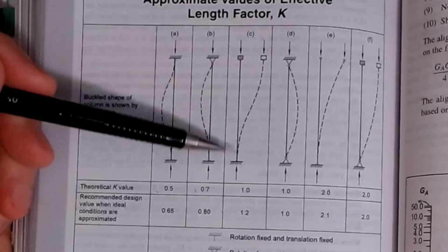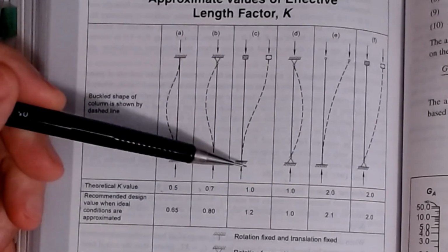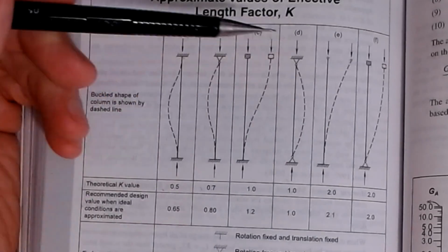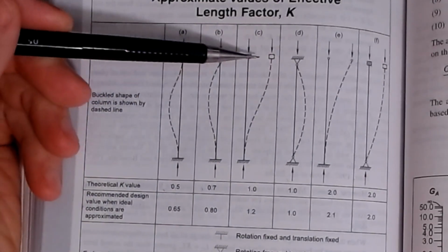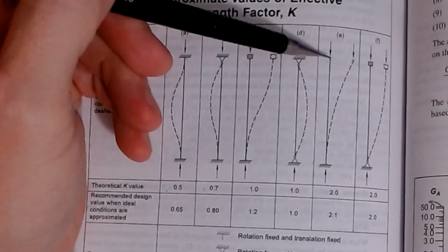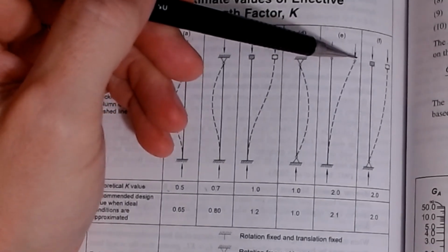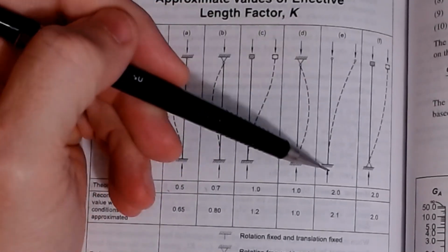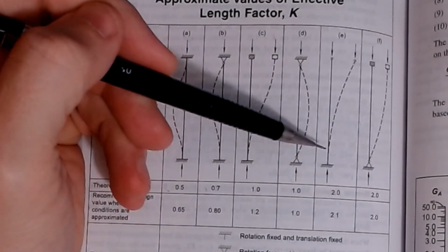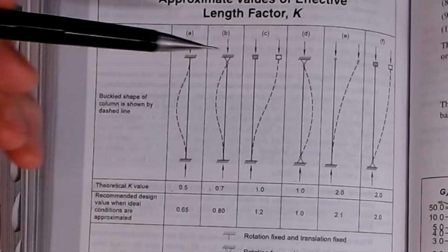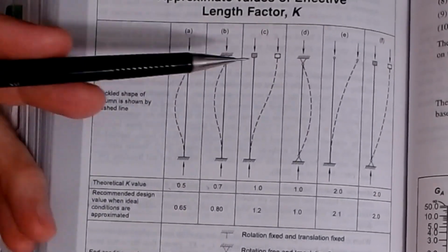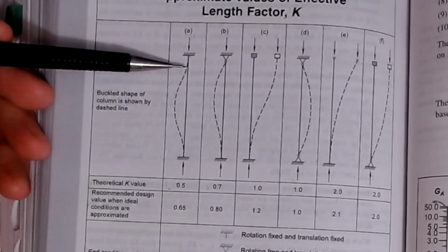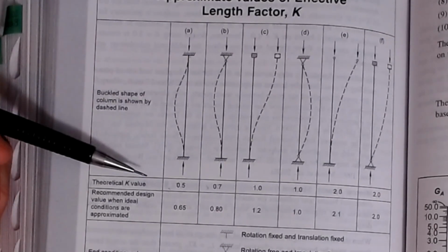We also had a couple of scenarios in which I had a fixed support at one end, and then it was free to do something at the other. Here it's pushing over to the side but not rotating. Here it is being allowed to rotate. And you can see that for this case, this is kind of our flagpole case, if you will. The K is actually 2.0 if it's perfectly fixed. But there are a whole lot of possibilities that exist outside of this table. What happens if I'm only partially fixed? It allows a little bit of rotation, but it's not truly free like a pin.